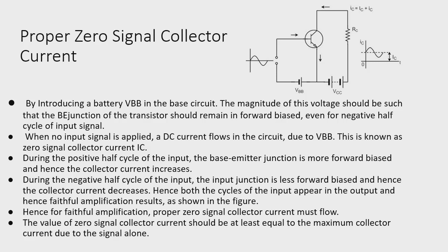Hence, for faithful amplification, proper zero signal collector current must flow. The value of zero signal collector current should be at least equal to the maximum collector current due to the signal alone.